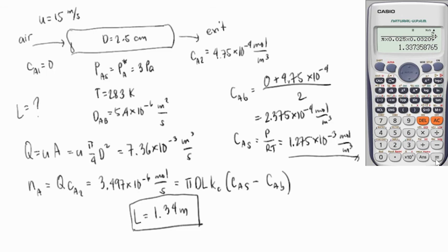So basically, if you increase the velocity of flow of the fluid, then the mass transfer would happen faster. In this lesson, we have covered convective mass transfer within the same phase. So in this example, our naphthalene is already in the vapor phase before it transfers to the air. Okay, so there is no change in phase. On our next lesson, we will be dealing with mass transfer in different phases. So that could be from liquid to gas or from gas to liquid. Okay, please do watch out for our next lesson.